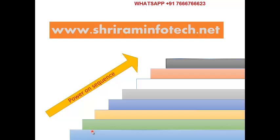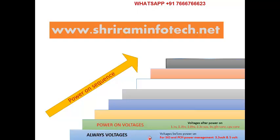Now we'll see a ladder here. Like in a desktop motherboard, there is a ladder. First, the always voltage is generated. As soon as you connect the adapter or a battery, 3.3 and 5 volts are generated. That is called always voltage, and this 3.3 volt is given to the SIO and PCH. When you press the power on button, 1.5, 1.35, 1.05, 3.35, graphics core and CPU core voltages will be generated.